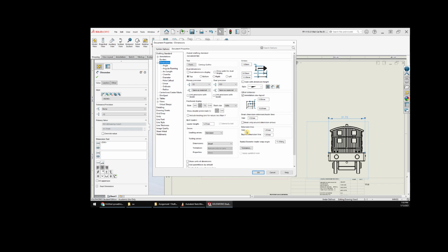the gaps in between the extension lines, tolerance settings, diameter leaders snap to certain angles. So if you put a diameter, if you've got a circle here, it will do snaps in 15-degree increments versus you trying to rotate it around. If you need more freedom, you want to set that to 0 because sometimes you want to work around other dimensions.